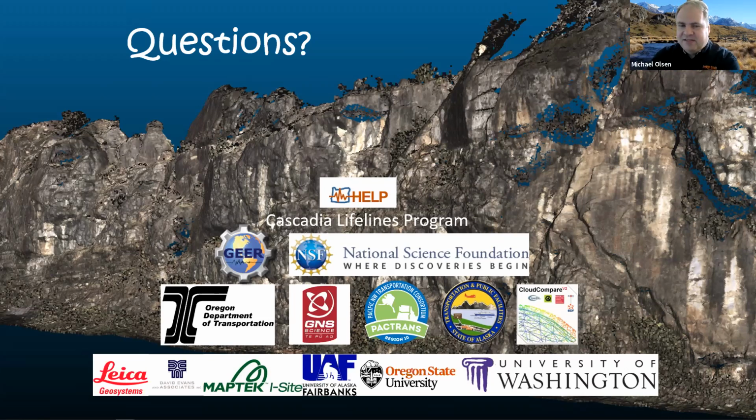Yeah, that's a great question. That's always the challenge: do you use interpolation, and if so, which technique? We published a paper a couple years ago that looked at the impact on the magnitude frequency curves, depending on whether you used interpolation to fill in those data gaps or not. There are definitely certain components, depending on the rockfall hazards and how big the rock chunks were, where that interpolation makes a difference. So we've generally done it both ways, without any interpolation and with interpolation, just to make sure things don't disagree too much and that we're not over interpolating.